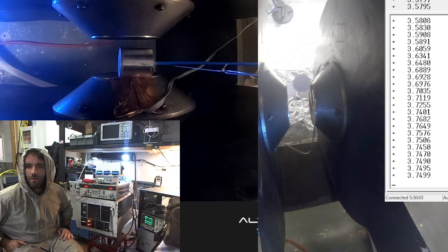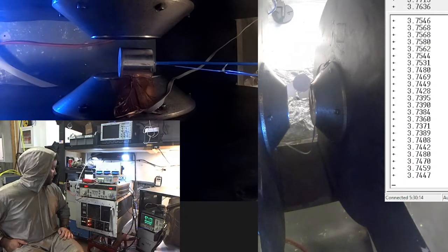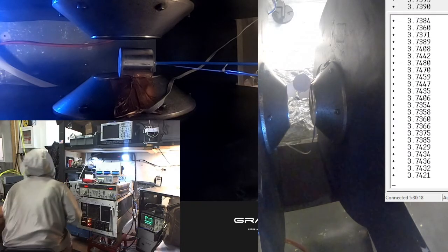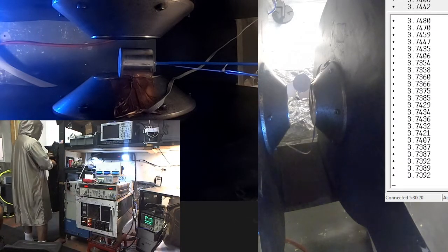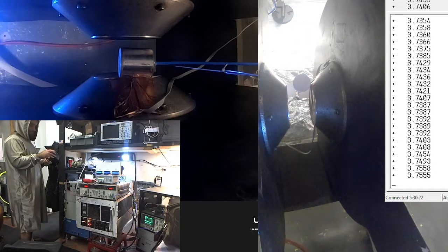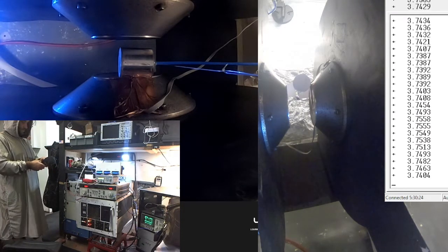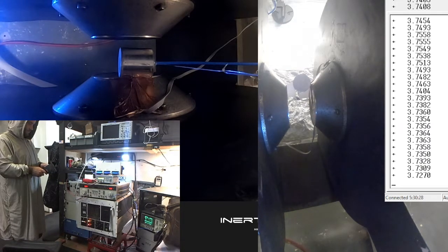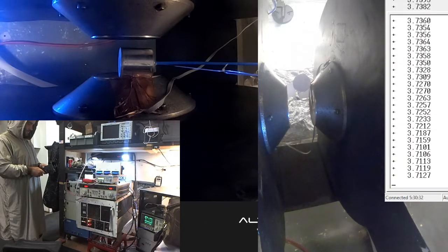I mean, if the cables or the coaxes are getting stressed out by the power input, and it might be flexing, I think we have our answer then. I'll get the thermal camera to take a view at it. Oh yeah, please do. I'm pretty sure we have our answer. That thing shifted. The cable is suspended by gravity alone. If it went right, left, up, or down, and it's entirely non-magnetic, it is clearly the coax producing this problem.